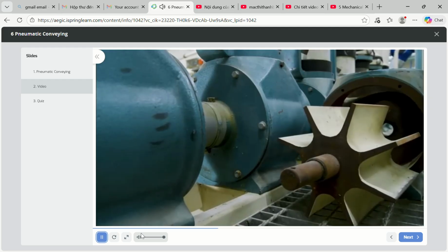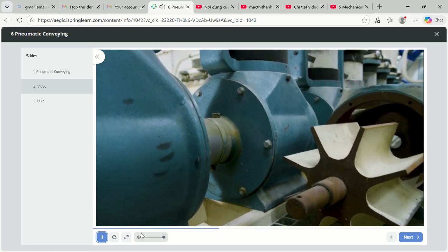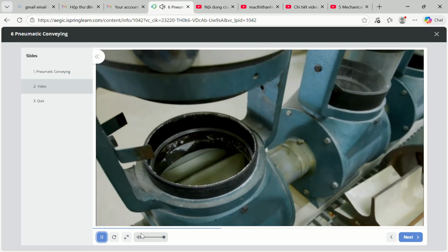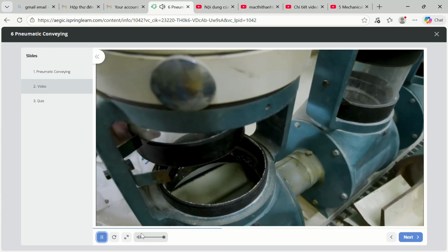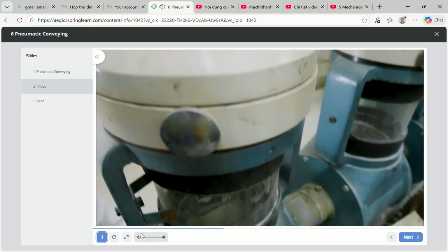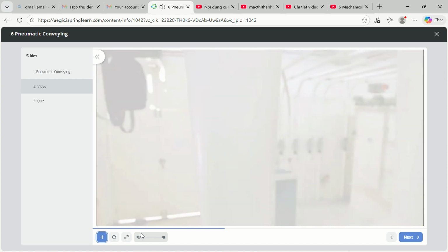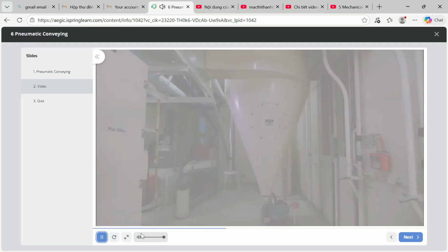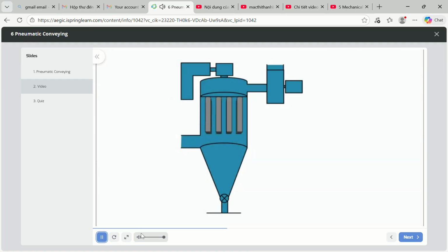The rotary seal consists of a shaft with vanes which span the outlet to create this airlock. The shaft rotates to allow solids to drop through from above. When large cyclones are used as filters, they may also contain fabric filter sleeves to improve dust extraction.